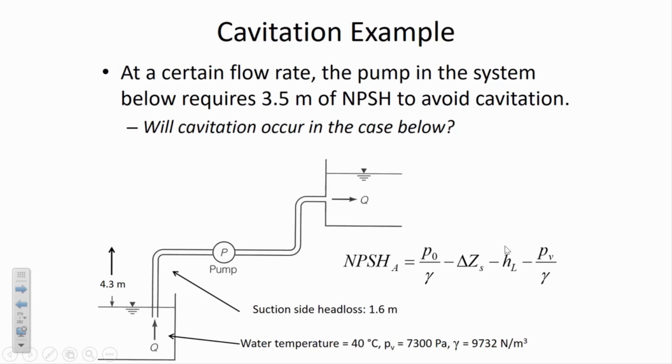So remember, under ordinary pressure, the vapor pressure of water at 100 degrees Celsius is 101,325 pascals. And so the vapor pressure goes up with temperature. If the water is 90 degrees, it's already so close to boiling that it's not going to take much additional suction pressure before it gets there. Cold water is further away from boiling. And cavitation and boiling are the same thing. It's the process by which liquid water goes into gaseous water, so water vapor.